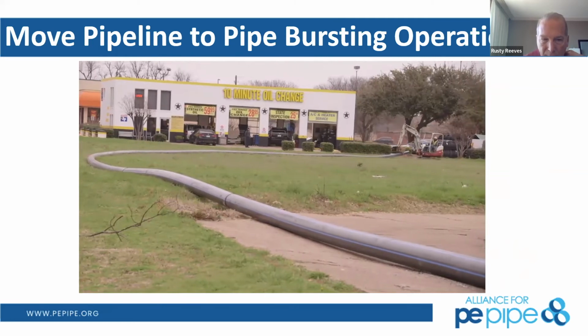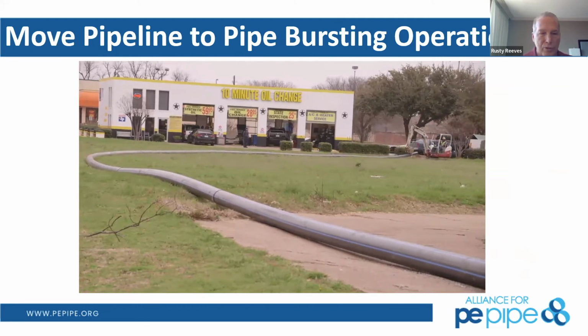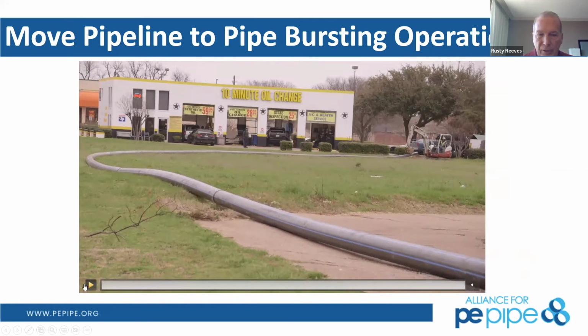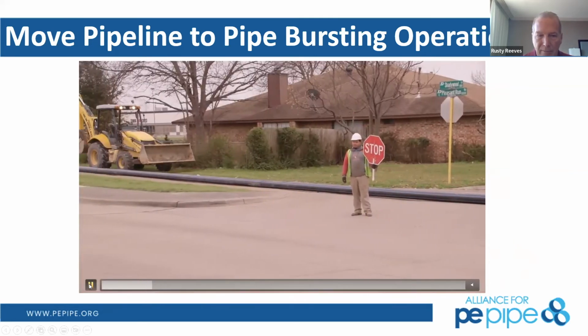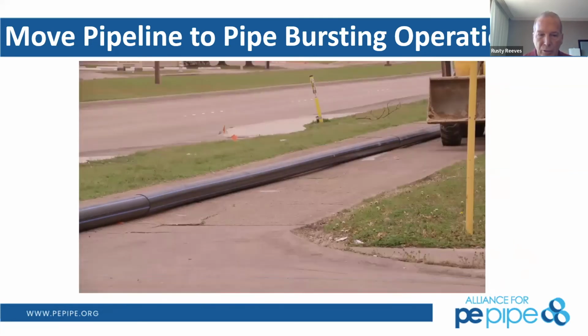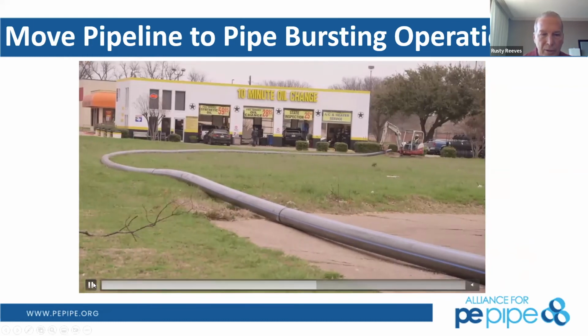The general rule of thumb is you can lose about 10% of that wall thickness and not have a problem with your operating pressure. It would still be good for the manufactured operating pressure, but it's very, very durable. Mines have used it for years. But yes, you do have to do some inspection and make sure you don't get too much of a loss there.